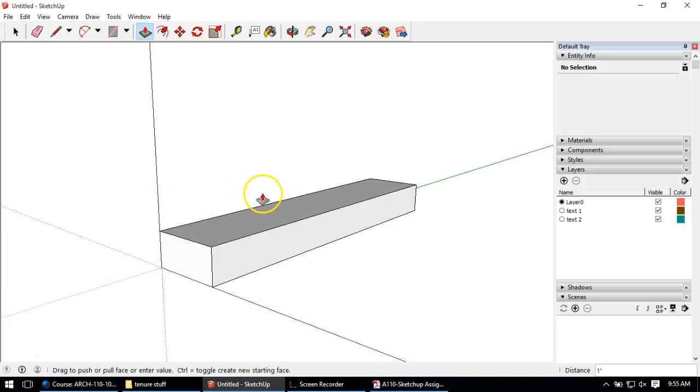The way that you should generally work is everything in SketchUp should be called something, a group. And that's because SketchUp is sort of sticky in many ways, and so putting things in groups sort of compartmentalizes them, makes them easier to move around and model going forward. And the way you make a group is pretty simple. We're going to go to the black arrow tool. I'm going to triple click on this to select the entire face. It's just 1, 2, 3, left click. I could also just draw a box like this. Either way, we can see it selected with the blue dots and everything like that. And I'm going to right click and say make group.